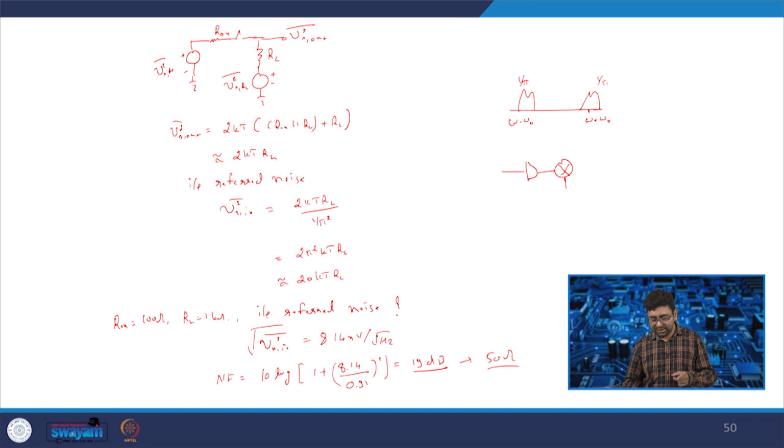We will also discuss how we can design an architecture which can remove the low noise amplifier, and we can design a mixer first receiver architecture. And mostly in the mixer first receiver architecture we are going to use this configuration of the passive mixer.